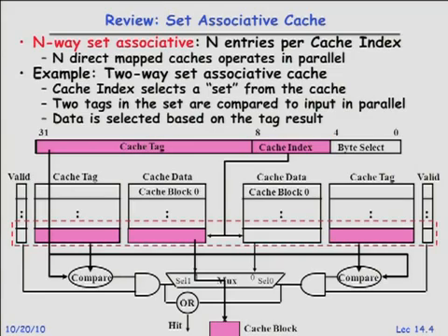Index gets smaller? Yes. Why is that? Because now you're four-way, so there's less blocks to choose from. Yeah, the exact way to think of that is if we keep the cache the same, this cache size has to do with the total amount of space here. If we go four-way set associative, each one of the banks is smaller by half, and so basically we lose a bit in the cache index by going from 2 to 4.